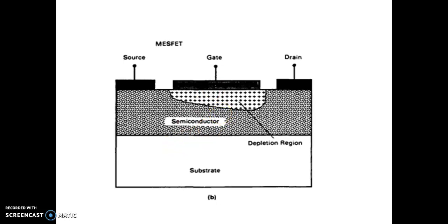The channel can be partially or totally depleted by the gate voltage and by the built-in voltage of the Schottky contact forming a gate. The isolation between the gate and channel formed by the doped semiconductor material is provided by the Schottky gate depletion layer that is controlled by the gate voltage.